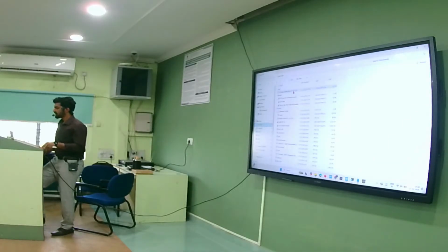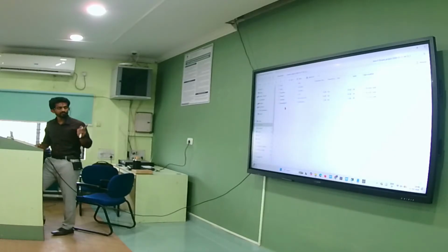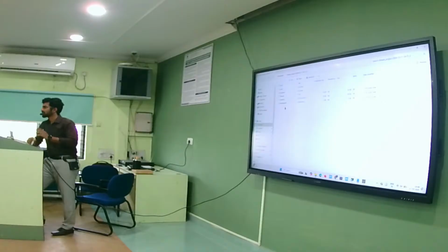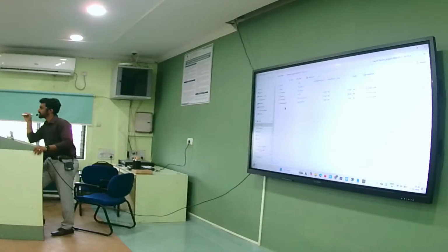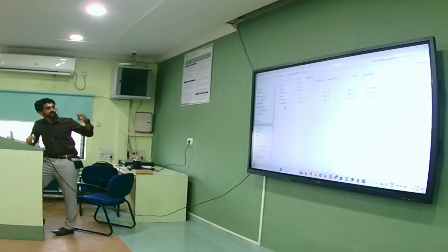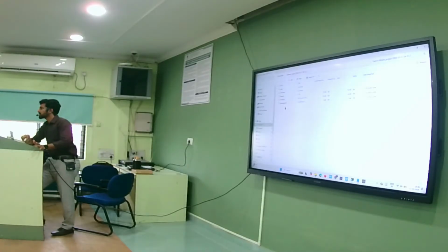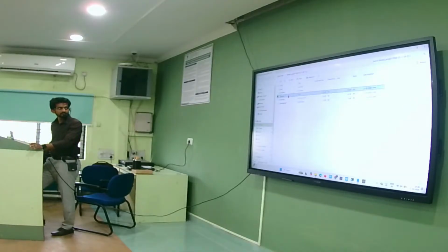See, this is the extracted zip folder, the zip folder which I am getting from deployment. One file will get downloaded, right? In the deployment stage, one ML model will get downloaded. If you open that package, you can see nano_ai.h, metadata, libnai.a. So nano_ai.h is a header file to use ML libraries from the Nano. So this is a header file you have to add. The .a file is an encrypted Python model. It's an encrypted way. You can't read it. It's a library file.